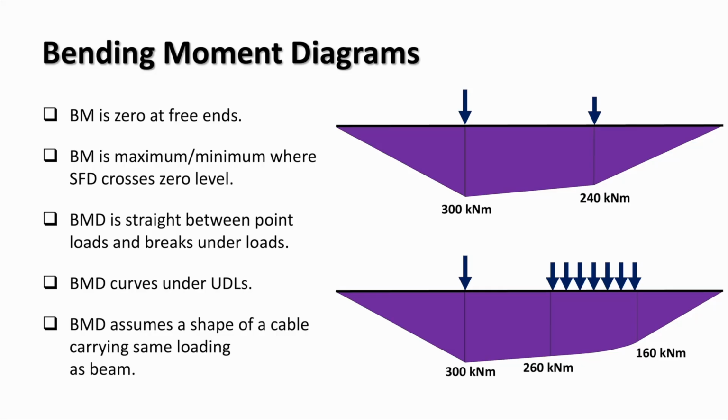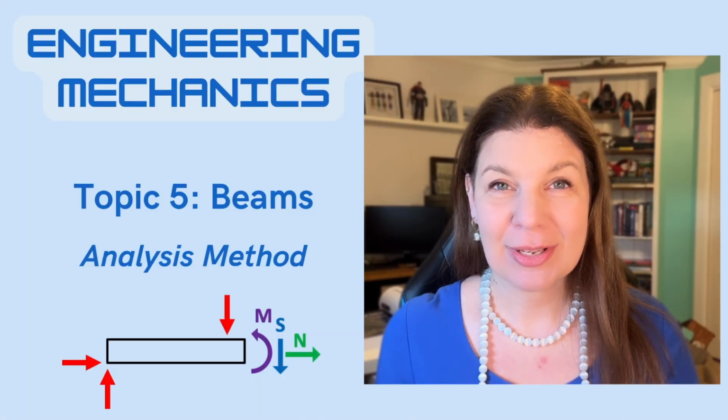Another useful visualization is that the bending moment diagram takes a shape similar to a cable carrying the same loading as the beam. Thank you for joining me.